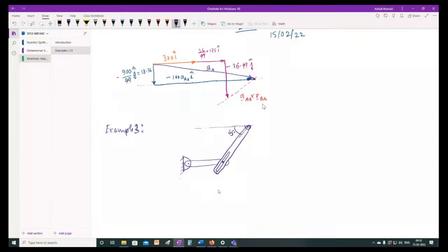Now if we give names, this point is C, this pin is A, the hinge point is O, and OD is the link. When the mechanism is running, if this is the crank rotating with angular velocity omega, then this pin with respect to this link is changing its position. That means the distance OA is not a constant.